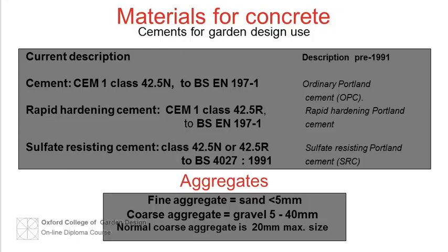The colour and strength of aggregates is unlikely to be of great importance unless they are to be exposed deliberately as part of the surface finishing of the concrete. For instance, granolithic or grano made with hard-wearing granite aggregate.